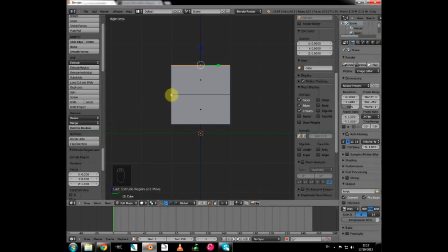If I extrude again, it will maintain the shape of the top faces, but if I pull the faces out, it will pull the bottom edge of this top face, so that this top face then develops an angle. I'll show you that by just making that face available by rotating the screen.